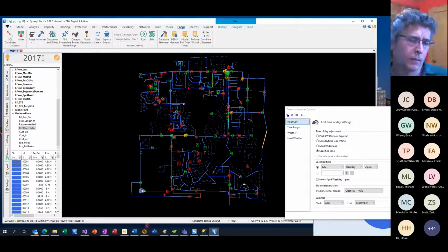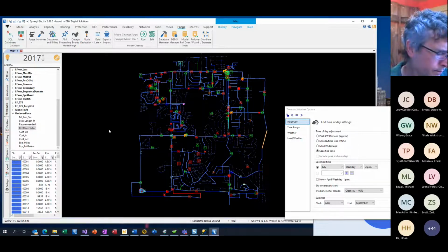And that can be pretty handy because I know a lot of you have really long section IDs. It's really tough to remember them or to keep a handle on them mentally. So the obfuscate can give you some more useful IDs. Now, if you do that, be sure not to save it back to your master model, because you wouldn't want to replace the master IDs and things. But it can be a handy tool.